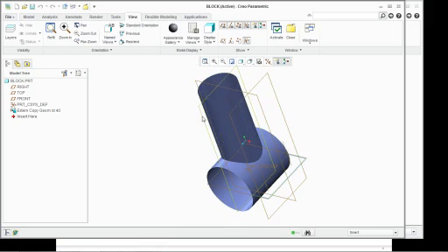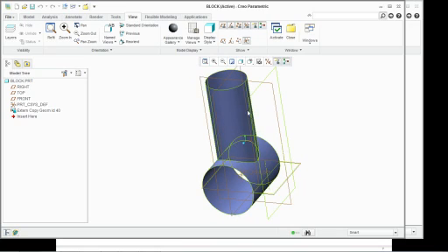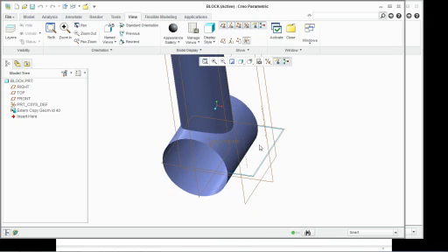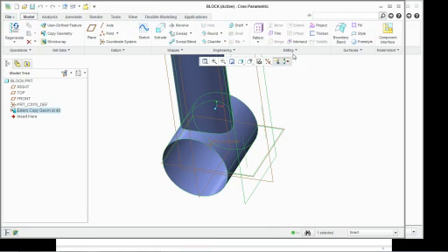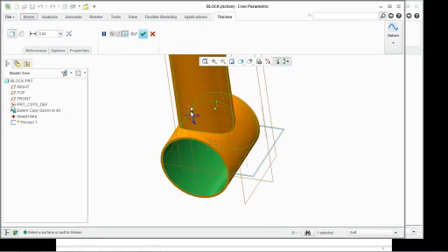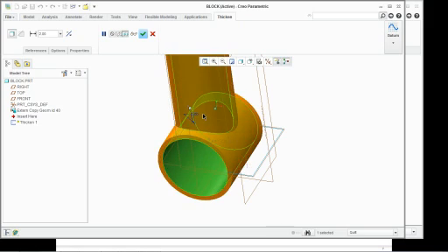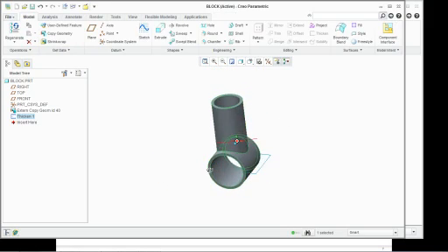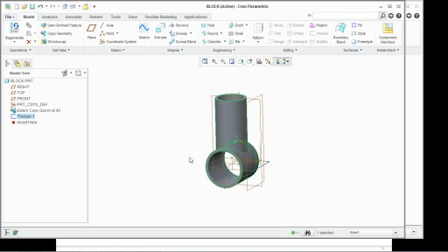It's another thing about Creo Parametric. They did update the colors a bit. So if you see something that's purple, that is a surface. It was blue because I copied it from existing geometry. So now I'm going to come in here and I'm actually going to create geometry from this. So I'm going to select my copy geometry, go back to my model tab and select thicken, give it a thickness of 2, and click OK. Now see, I do have a solid part now.